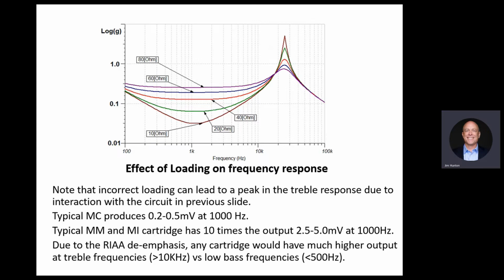What's the ohms? The resistance of the entire cartridge? The termination resistance of the cartridge. Your preamp, especially MC preamps, will have different ohm terminations, and you pick the one that's closest. Unfortunately, some of them have the lowest at 50 and the cartridge requires 20, or the lowest is 100 and the cartridge is 50.